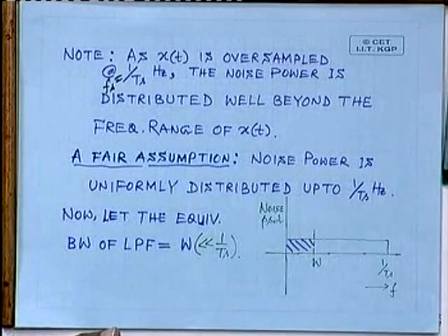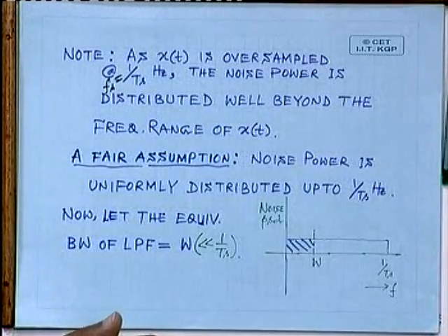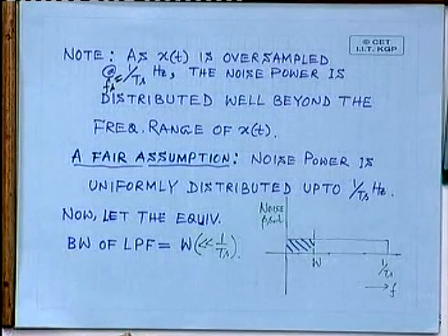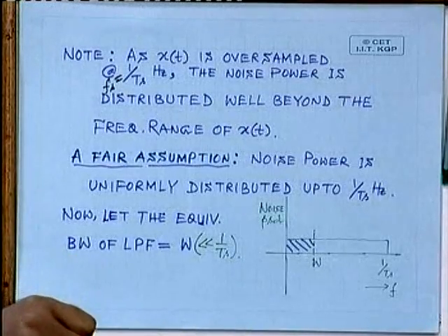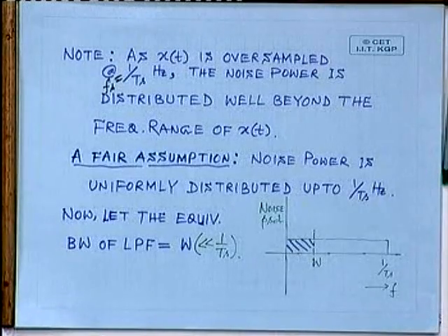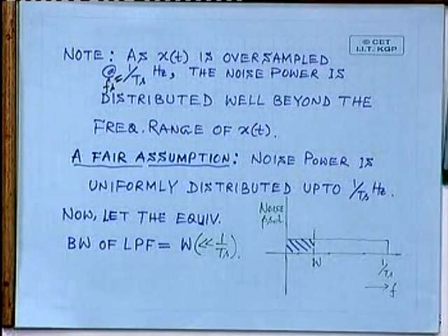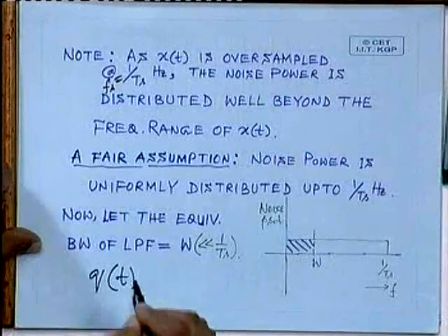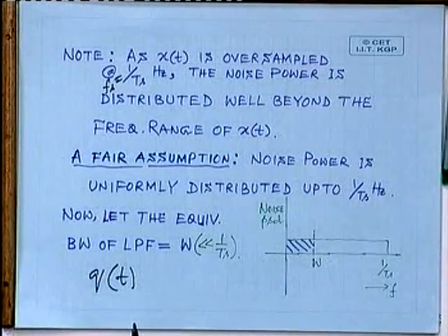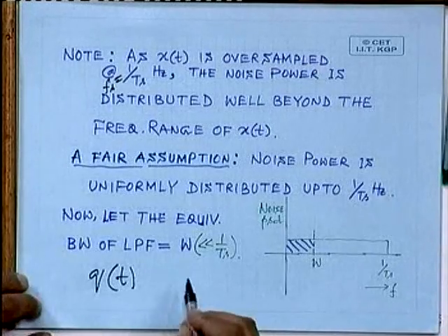Do you accept? Because if you try to visualize the quantization error, I am talking about q(t) really, as it changes with time, it is limited between plus s and minus s, but the error is getting updated very fast. So if you go for some kind of analysis, you will find that the power spectrum of the signal stretches much beyond the signal frequency range. So that is the spectrum of the staircase approximation. No, the quantization error. What is the quantization error? Q of t, how is it changing? Can you just sketch it?